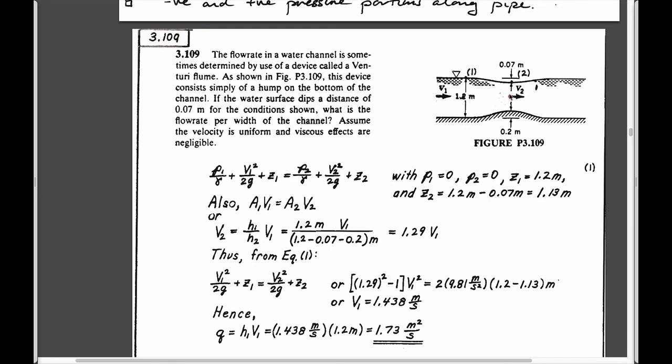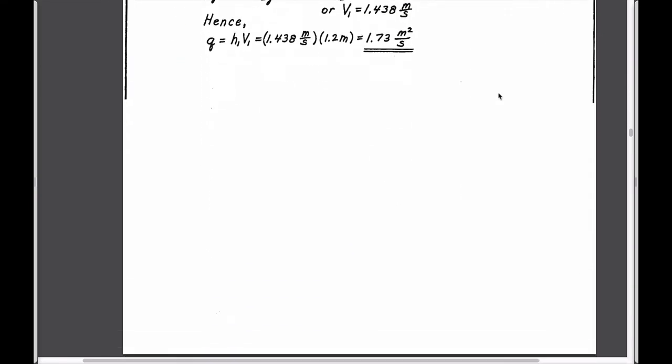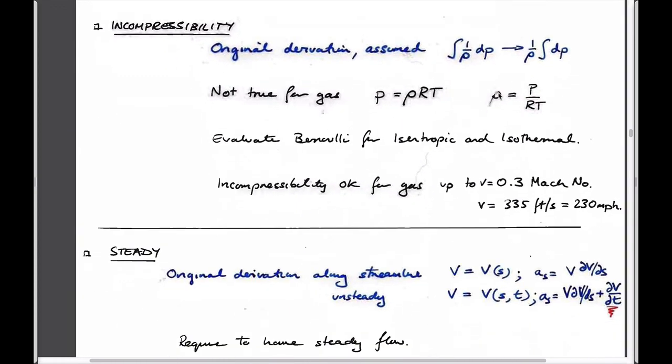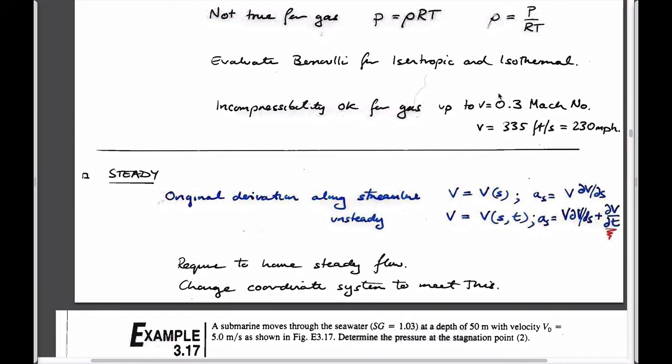And if it increases to go through this, you can calculate what the actual dip of the water would be as you go across this, just by using both Bernoulli and also, since you have two velocities which you don't know independently, you have to link them through continuity. And so you'd expect that water flowing across a hump in the base of the bed would give you a dip in the elevation.